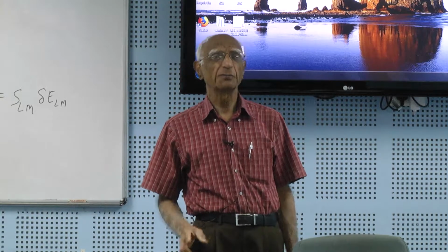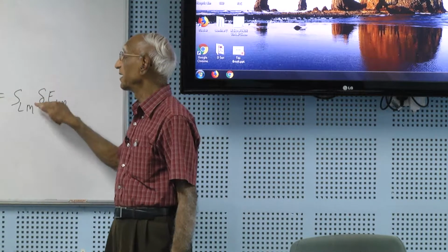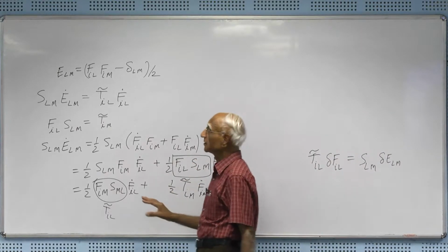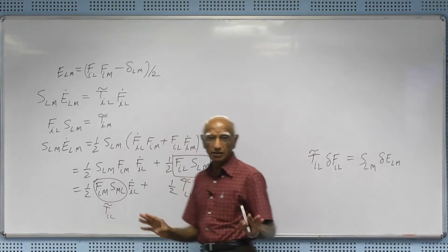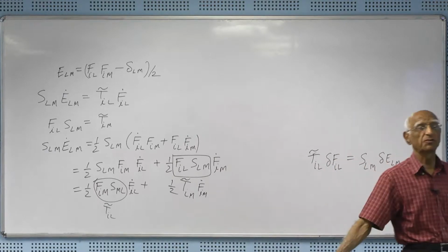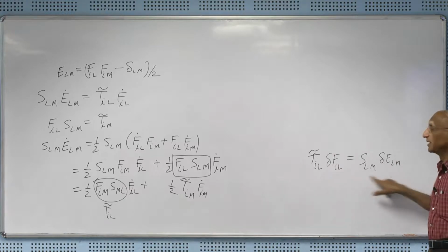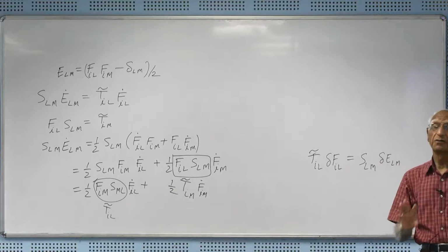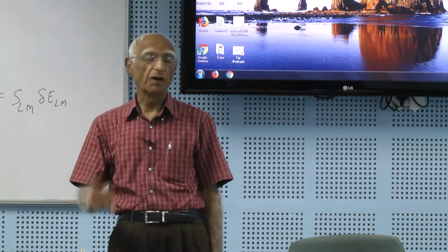I think some of you asked me about von Karman nonlinearity. The von Karman nonlinear strain is not quite E_LM, actually it is not, because you neglect some quadratic terms in the displacement gradients. Therefore this equality does not strictly hold, and there is no stress tensor that is work conjugate of the von Karman strain tensor.